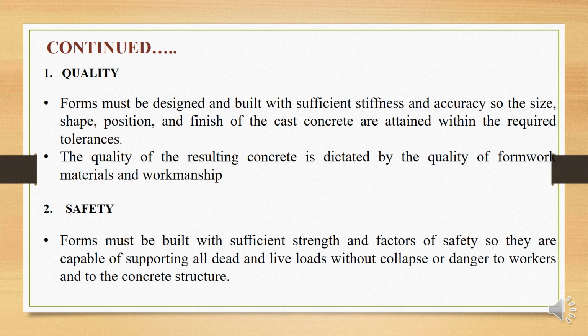The surface of concrete is disfigured by fins, and cement paste loss and honeycombing may result adjacent to the leaking joints. So, the final shape of the formwork in contact with the concrete should be arranged and joined so as to produce a concrete surface of good appearance. In some cases, a provision of special form lining may be necessary to achieve the desired surface finish.